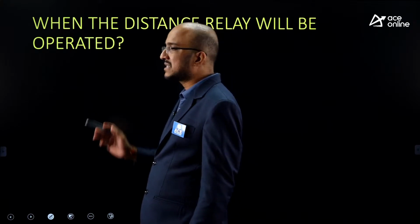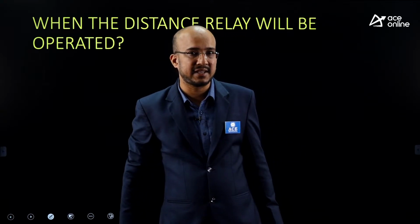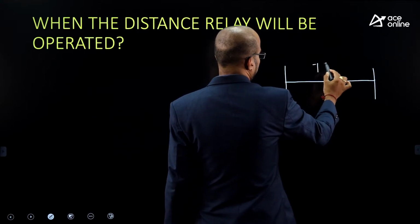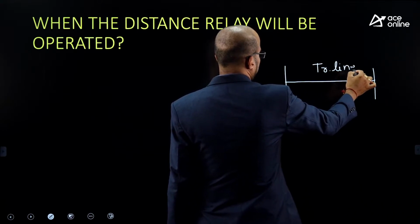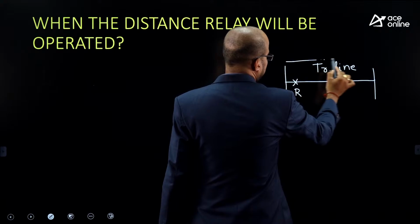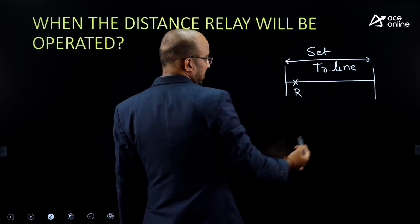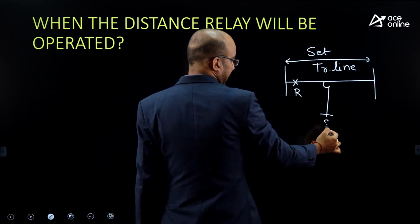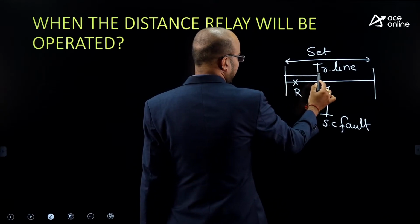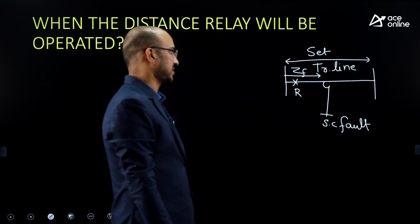The distance relay will be operated whenever the distance seen by the relay is less than the set distance. Suppose you are protecting this transmission line using a distance relay, placed at this location. During normal condition, this is the set distance, this is the set value. So, when a short circuit fault takes place, the observed distance during fault will be less than the set distance.